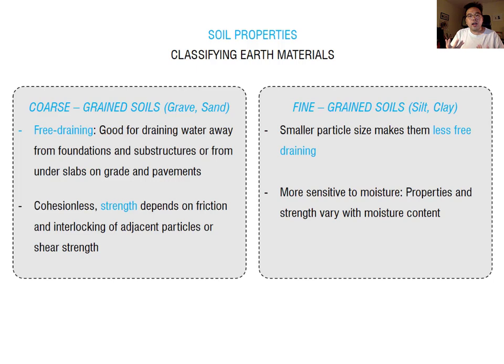But fine grained soil, which is silt and clay, is less free draining compared to coarse grained soil. Because its particles are small, it tends to contain water. So water can change the volume because of frost action, and it is also more sensitive to moisture.